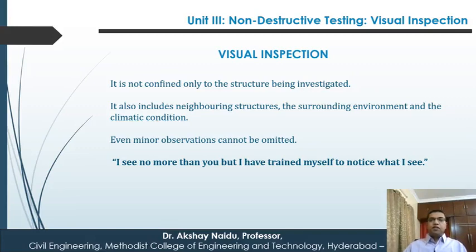Near the ocean or a water body, water may be mixed with salts, and during construction phase itself, the water that might have been used might have a high content of salts, which cause the deterioration, and the surrounding weather conditions they affect.